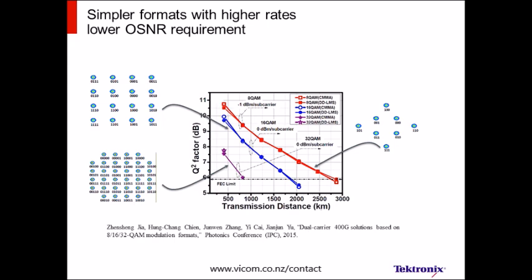As you go to the higher QAM levels, you can reduce the baud rate, and so that's going to let you get more channels into a particular fiber. But the higher QAMs can't go quite as far, and so you might have to trade off the total data throughput of that fiber just to be able to go the longer reach.